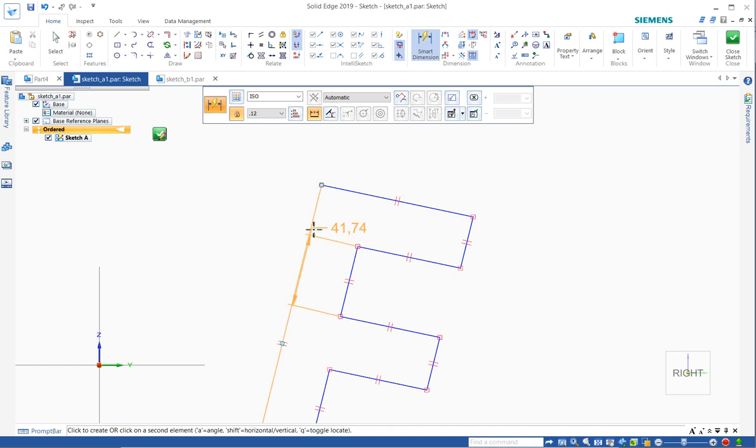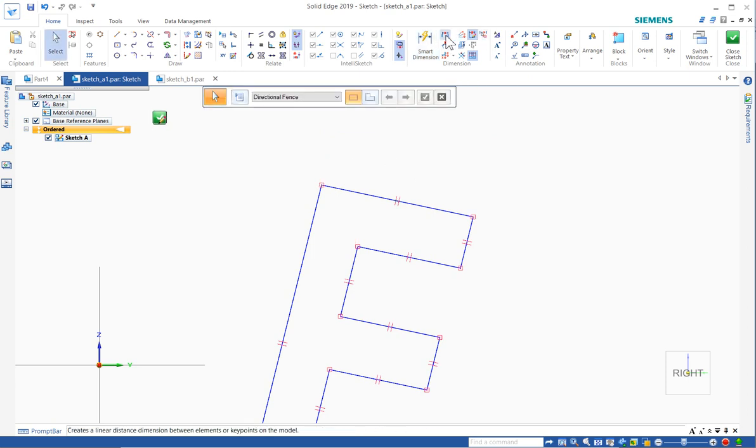This is usually where I like to show people the difference with dimensioning. If you try to dimension this from here to here, you'll get either a horizontal aligned, or if you hold the shift key down, you'll get a distance between aligned. But if you wanted it to be lined up with this particular vector, you'd have to use dimension axis as the method.